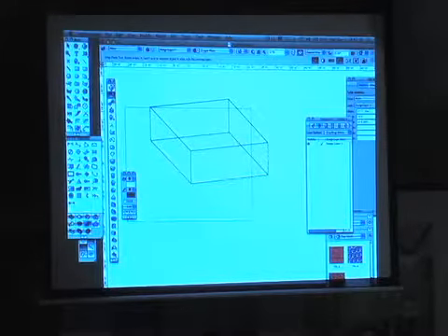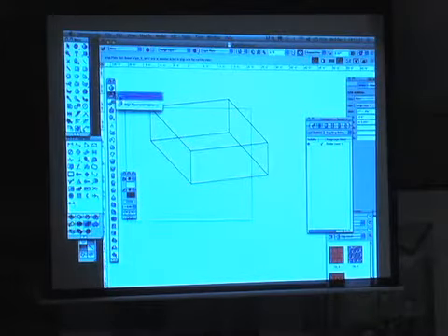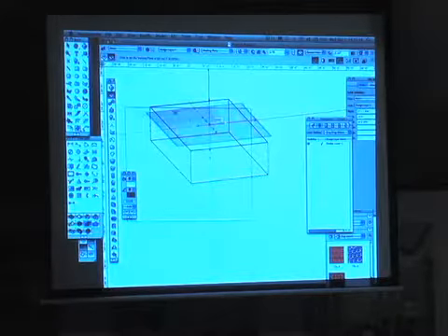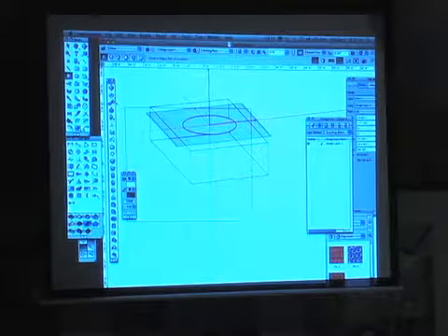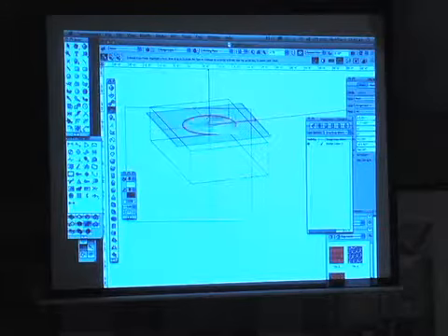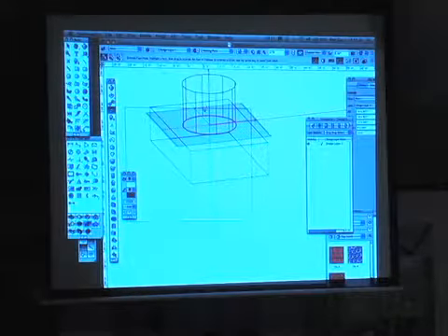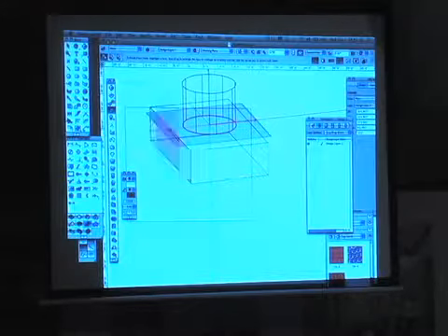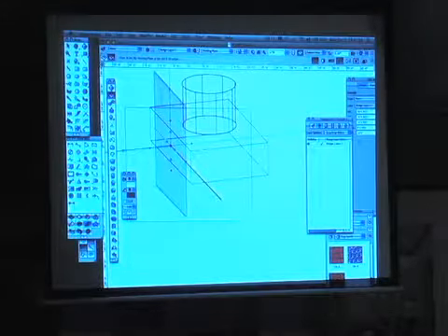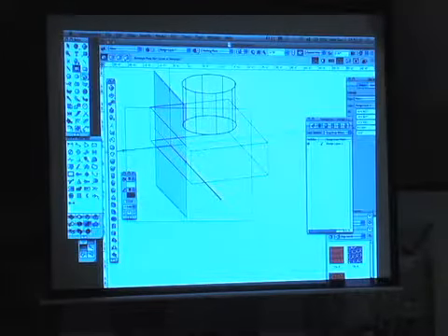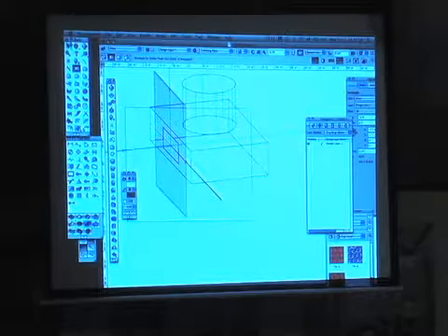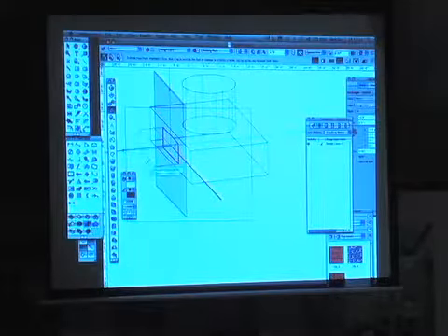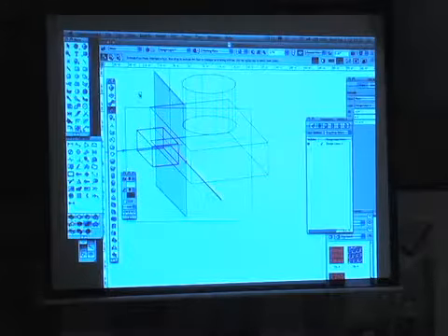Again, the working plane is important. So now set my working plane to the top here, draw a circle on top, go back to my push-pull, Shift-R, and I'm working right here on top of the model. Shift-I is my other shortcut for the working plane. Shift-I, you said? Shift-I. Draw a rectangle here on the side, Shift R, my push-pull.